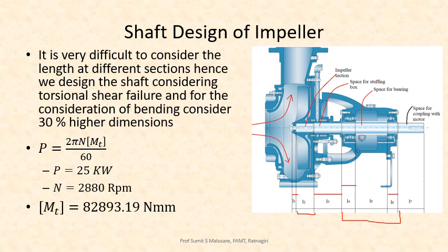It means this bearing won't carry any axial load, only radial load, and the bearing at the exit carries the entire axial load and a very small amount of radial load. The last part, L7, is the space for the coupling, where the coupling is to be fitted. This is the entire loading arrangement for the shaft.